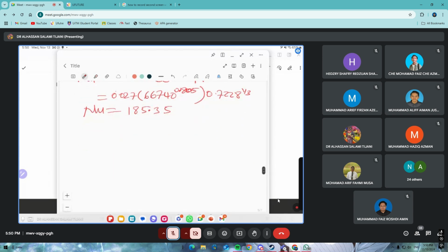So based on this information now, we know the general formula for Nu equals hD divided by what? k. So now h equals Nu times k divided by diameter.